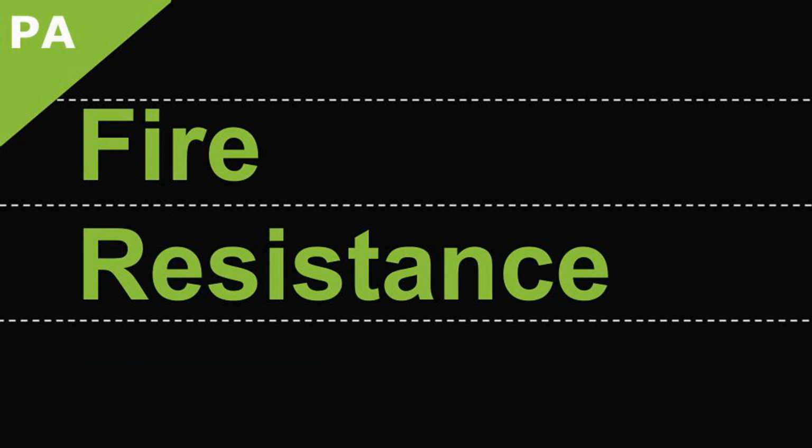Fire resistance. Fire resistance is the property of a material, finish, or assembly to withstand or resist the spread of fire and provide protection from it. These requirements are located in Chapter 7, Fire and Smoke Protection Features, Section 703, Fire Resistance Ratings and Fire Tests.